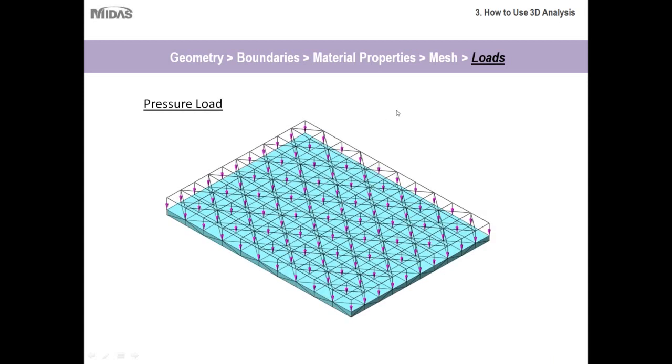And then same with pressure loads. So for those of you who are wondering how we're able to model 3D loads, you can model a distributed load such as this by selecting a certain face, and then the program will automatically select the nodes and apply the forces along a distributed plane. And say, for example, if you had a more complex loading type with a higher level of loading in this area as opposed to this area, there are certain things you can do to manipulate the program to produce that asymmetrical loading.